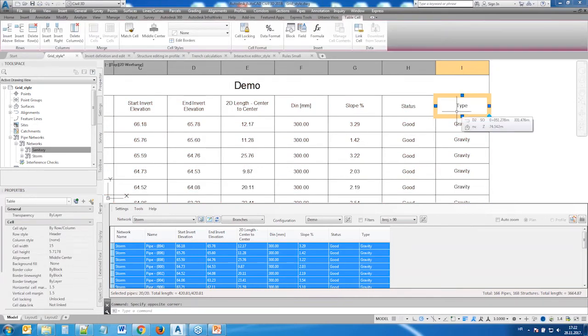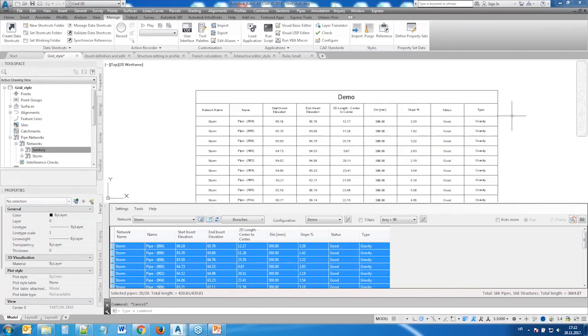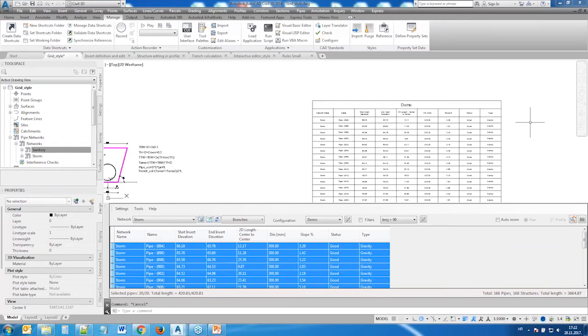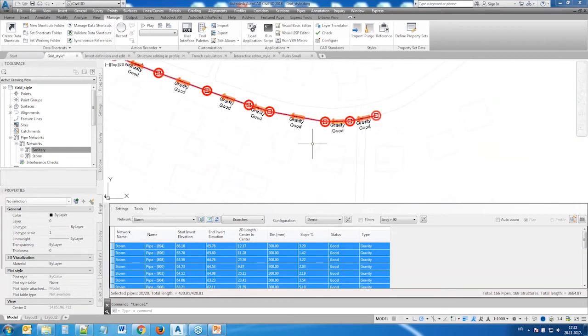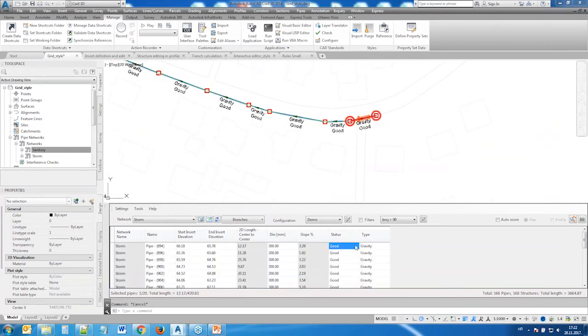And another thing which is quite important for all of you that know this: this is actually an AutoCAD style table. It's not a Civil 3D style table. So you will recognize the ribbon up top. So you have all the editing possibilities of AutoCAD tables. You have the formulas and everything which is connected with AutoCAD tables. So basically, we create an AutoCAD table and put Civil 3D data into this table, which is again something you cannot do with just your standard Civil 3D.